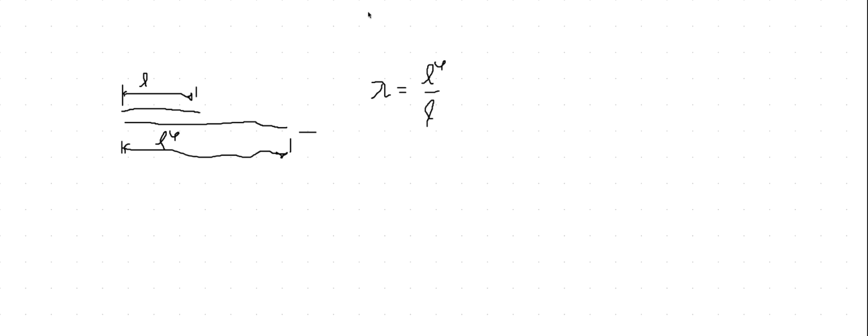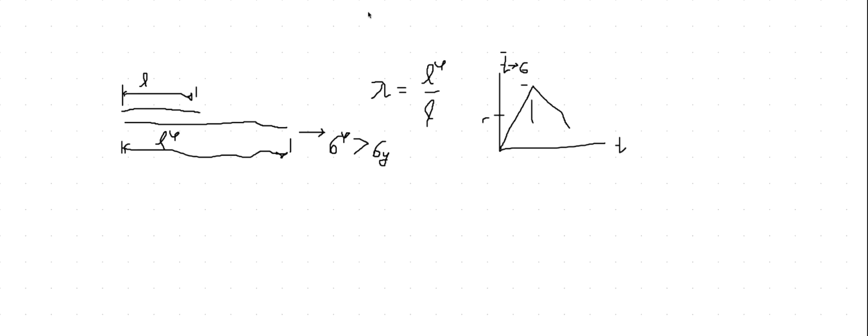So in order to stretch this, of course, you need a sigma, in particular sigma phi, the true or Cauchy stress, and it happens to be larger than the yield stress. So you're plastifying. You stretch it so much that you started plastifying the thing. So they say, okay, basta, this is my loading program in terms of the application. I apply up to a certain point and then I put it down. So this is, let's say, the traction that gives you the stress. And this is your time. First you do it up to the maximum value, and you pass in the process sigma y down the cross section, and then you reduce it down to 0.